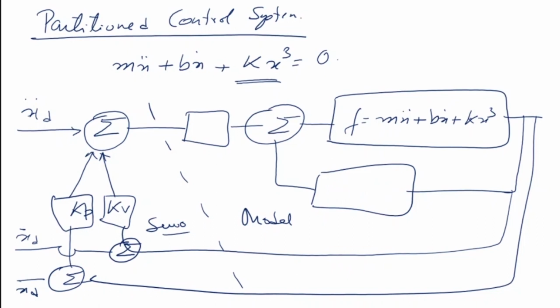In the case of mass, we put D(theta) there, that's my inertia tensor, and here we say it is h(theta, theta dot) plus g(theta) plus J transpose f. This is a way where we can partition the dynamic equation and use this partition control system to control it.